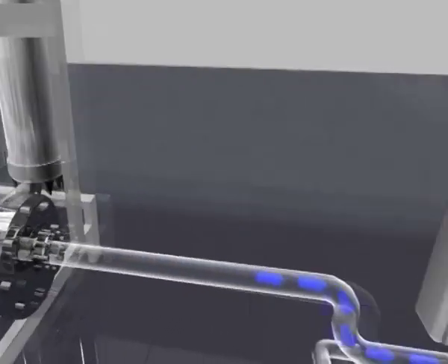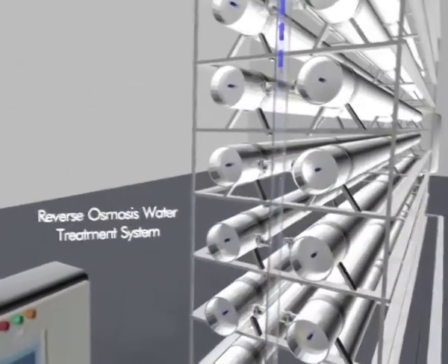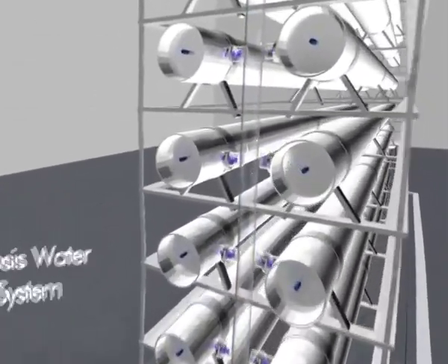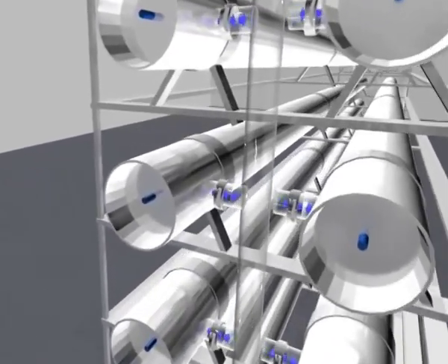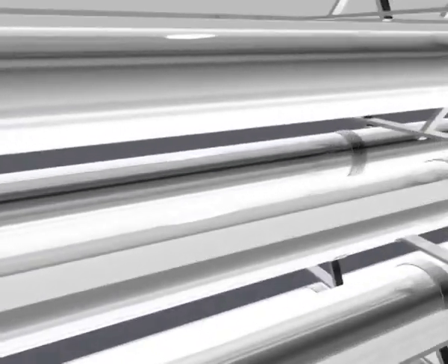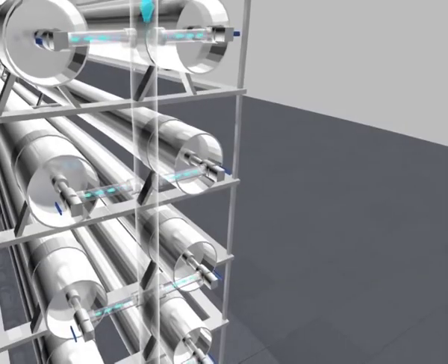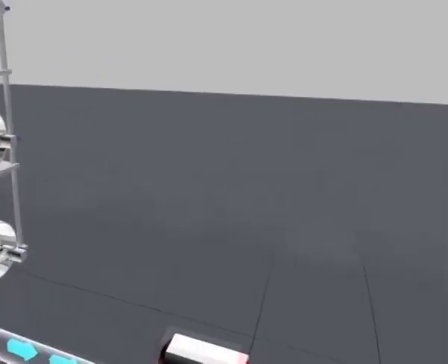Purified water so produced shall be used for all operations except washing and cleaning where potable water may be used. Water shall be stored in a tank which does not adversely affect quality of water and ensures freedom from microbial growth. The tank shall be cleaned periodically and record maintained.